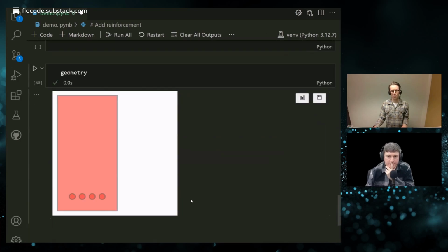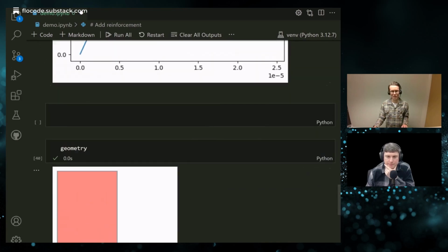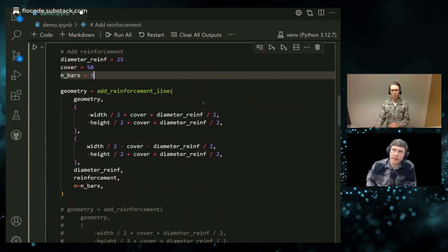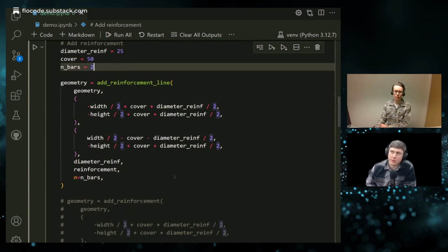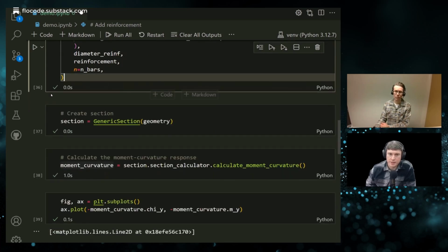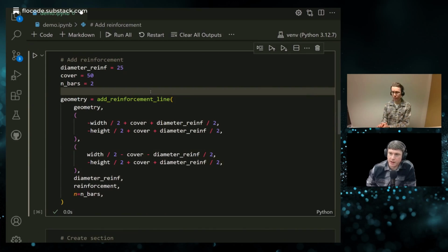Okay, this is quite heavily reinforced, or they're quite close to each other, so perhaps not the best design. And would something like that, for Eurocode in particular, would you get some sort of error code to say you've tried to place 4 bars in this relatively narrow section, the spacing is inadequate, or some sort of warning code like that?